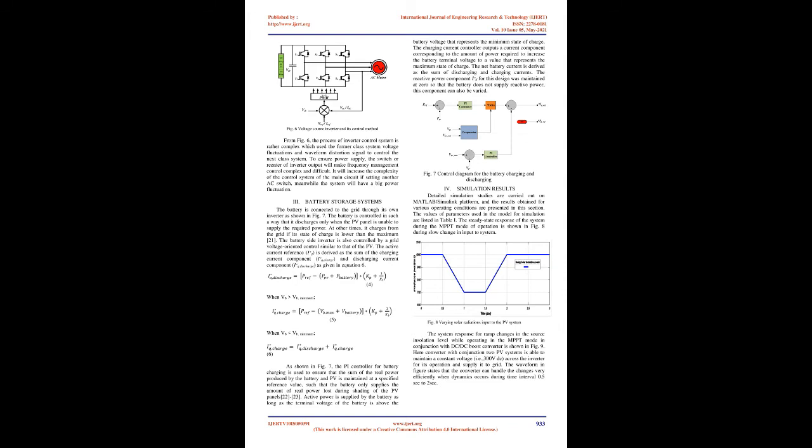Voltage source inverter control method. The PV array's working voltage is set to VO. The standard voltage VREF should be matched with the working voltage VO when the PV array is in the maximum power output state. The standard current IREF should be kept sinusoidal while the power factor should be kept at 1, which can be realized by the PWM control method. SW is a switch which mainly protects the inverter, and cuts the inverter from the system when the system power is off. The voltage source inverter and its control method are shown in Figure 6 below.